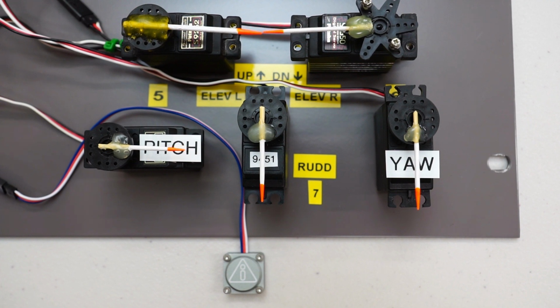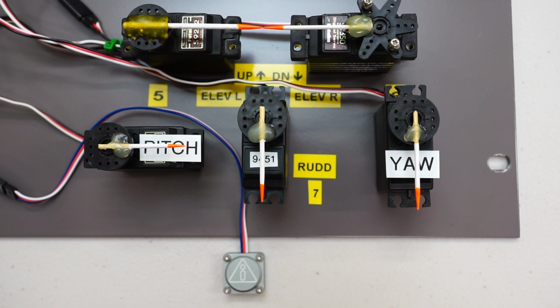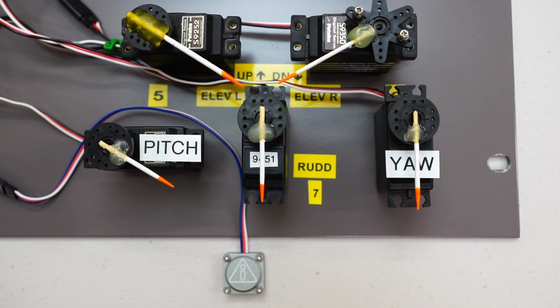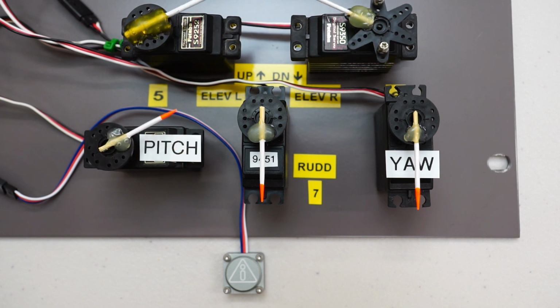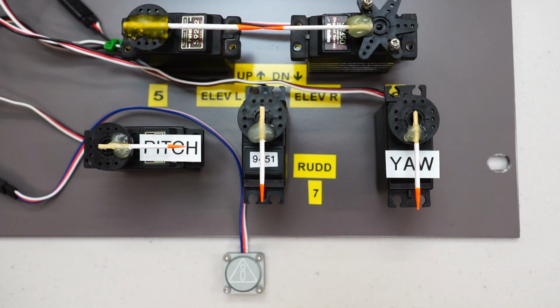And that's tied to my elevator stick. So you've got the two elevator servos up the top of the screen. We've got up elevator, down elevator, and the nozzle follows the same, or basically the pitch servo in this example has to follow the same sense. So that's correct. And just to prove it, I've still got the original setup.